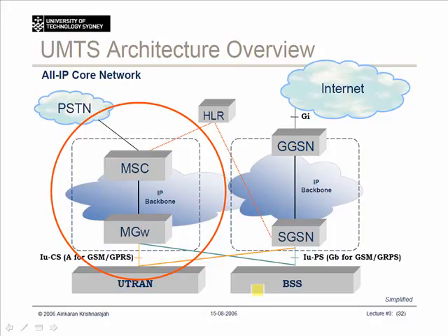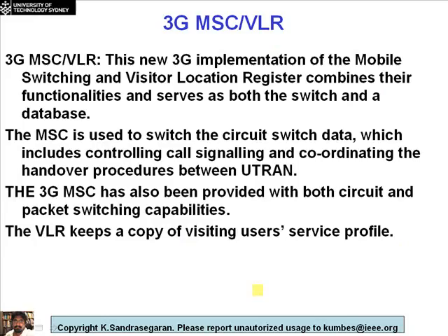Okay, so what's the main function it performs? Switching. Yeah. Okay, it's a switching center. It essentially takes information from one time slot on one TDM input and puts it in another time slot in another TDM output. That's essentially the main function. The switching function is an important function that the MSC performs. It's the same MSC that we are dealing with, the same MSC that is more than 10 years old, most of the time. So it essentially performs switching in the time domain.